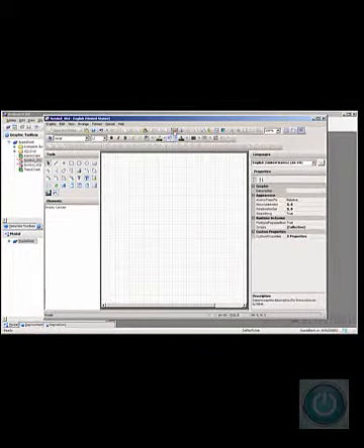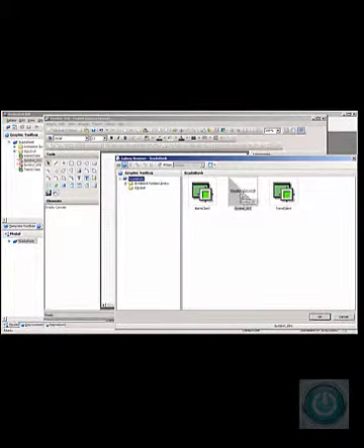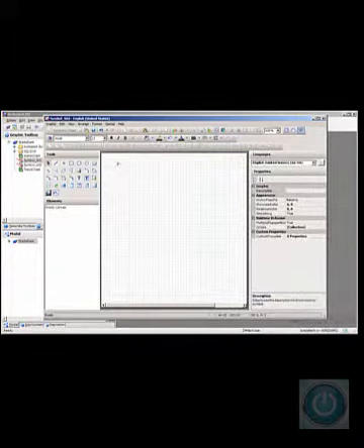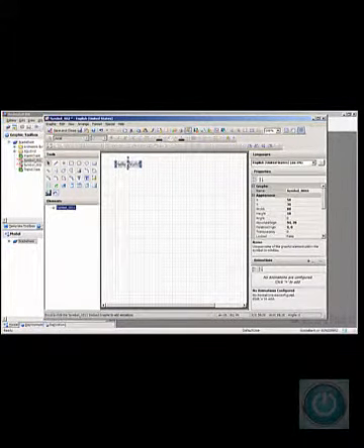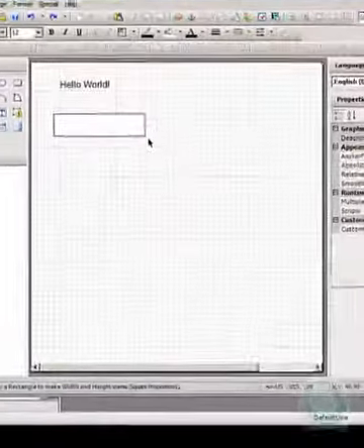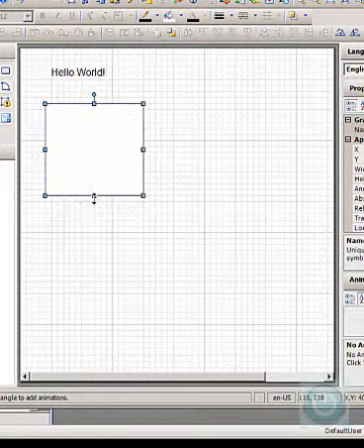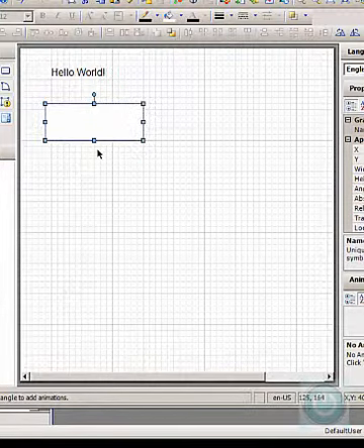But watch what happens when we place that same ArchestrA graphic inside another ArchestrA graphic. The aspect ratio goes back to being unlocked. This is the difference between having it locked in WindowMaker and having it locked in the ArchestrA editor. You can see the same thing happening when I draw and resize this rectangle. But there is a way to lock the aspect while developing.